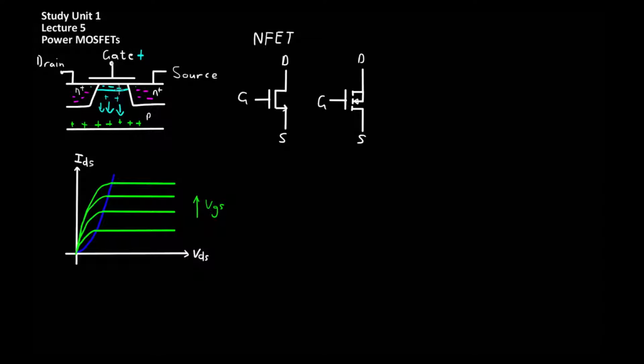current to flow correctly. Shown here are the idealized MOSFET transistor characteristic curves. It is a plot of the drain source current versus the drain source voltage for various values of gate source voltage. So for each fixed gate source voltage, the current will increase, forming this curve.